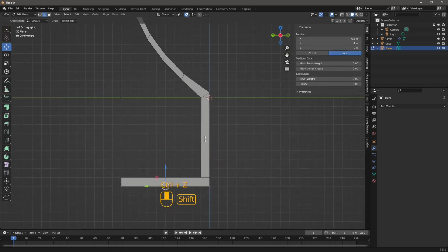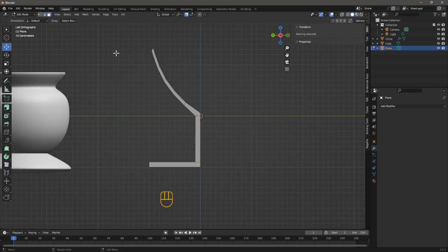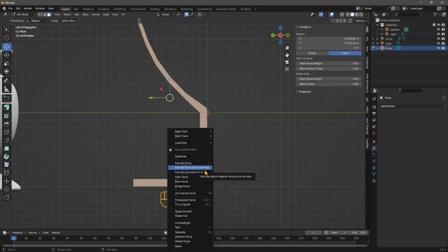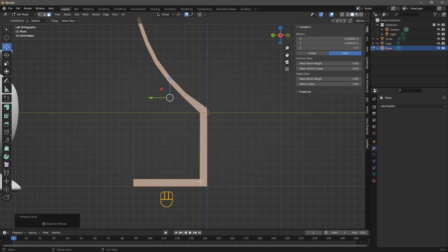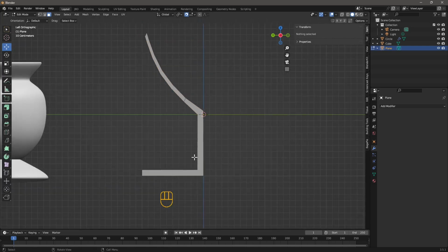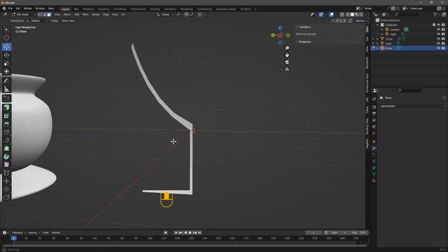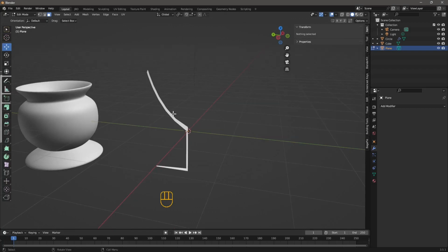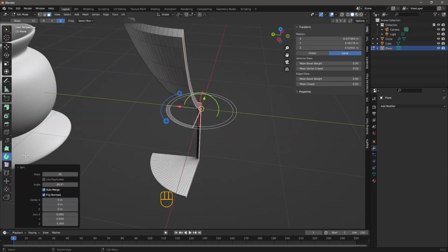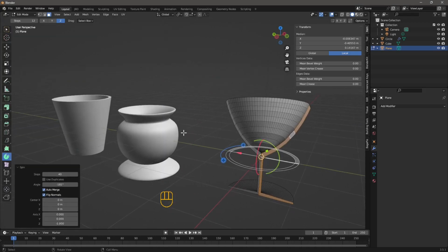So what we're gonna do is select all the faces and right click, and let's do the dissolve faces. So it's gonna get rid of the extra cuts that we don't need. Once you merge and dissolve many times to get rid of all the separation lines inside, you can proceed with the spin, and then we can continue with the other tools that we know in Blender to proceed with our work. Now we're gonna stop here.